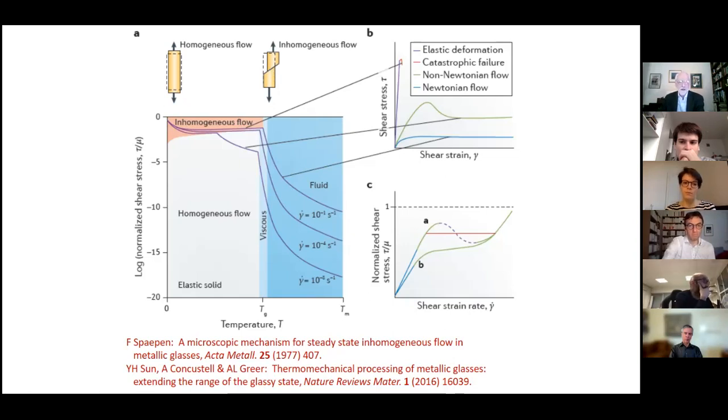And that's generally associated with the phenomenon shown top right, that for a metallic glass put under increasing load and getting increasing strain, you go from elastic to plastic, but as soon as you enter the plastic regime, and again, unlike a polycrystalline metal, you soften rather than harden. And that's what gives you the instability, of course.